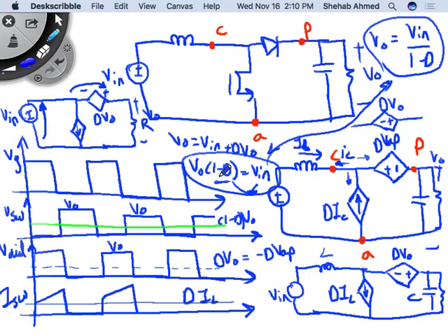Then in 420 you will put this on steroids. You will improve the dynamic response by changing the controller, for example. But at the end of the day, change controller, don't change controller, if you have a big capacitor, it's a big time constant. You have a big inductor, it's a big time constant. So there will be a limit on the physical system, just because you try to increase your proportional gain in the controller.